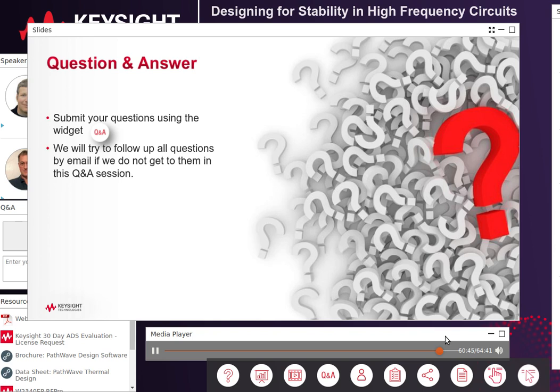You can actually use an AC simulation or a harmonic balance simulation to do EM excitations in general. For harmonic balance, it can be a little bit tricky because you need to get the right harmonic mixing term to land on the frequency that you want to analyze with the EM. So in the example, we wanted to analyze something like 3.4 gigahertz.